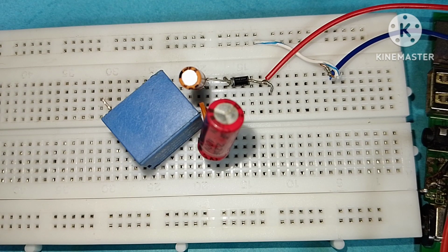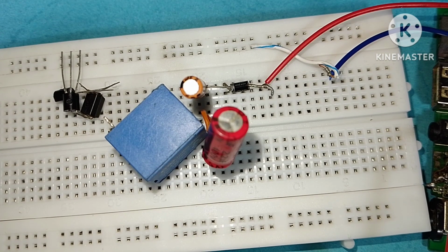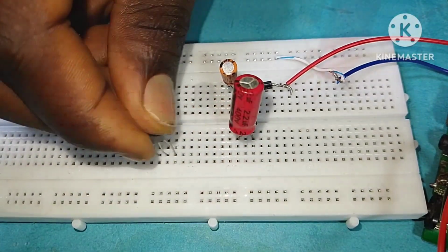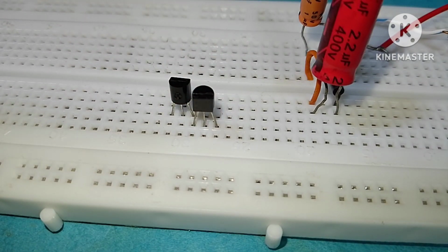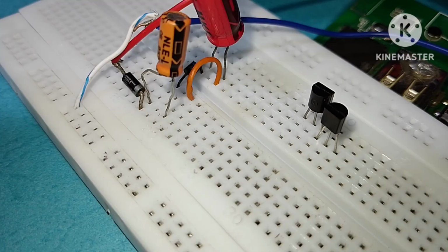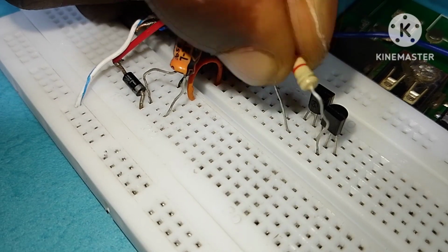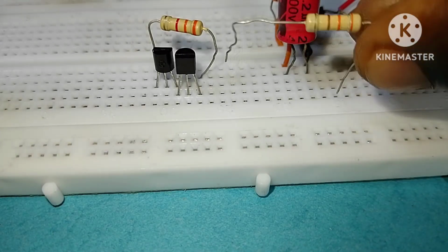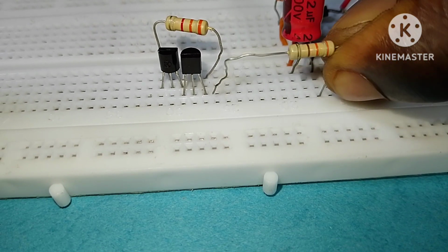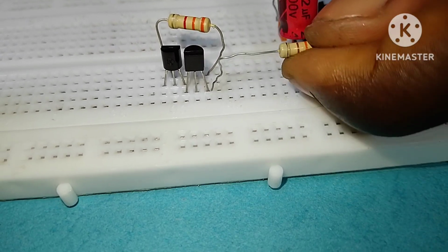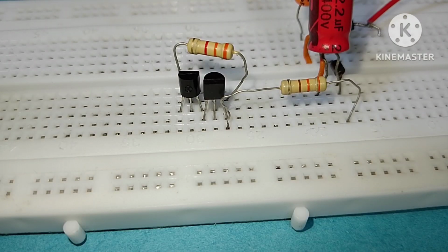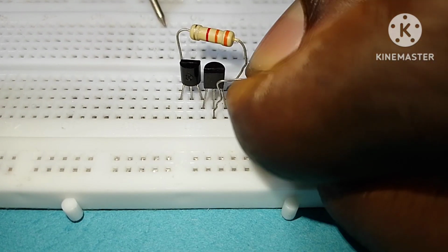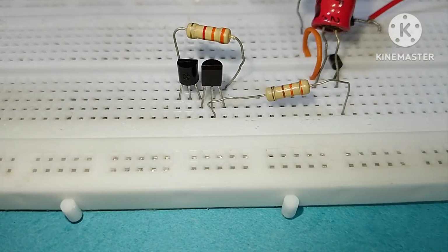So we need our 3 switching devices: the relay, optocoupler, and transistors. Placing your BC547 like this, and the next connecting their 2 collector leads in contact with each other. The 2 collector pins in contact, and placing a 33K to the base and emitter pin, and also with a 330 ohms resistor to the positive side of the capacitor and one of its leads to the base pin of the transistor. Not this way. Wrong. I said the base pin. So taking this and hooking up into the base pin.